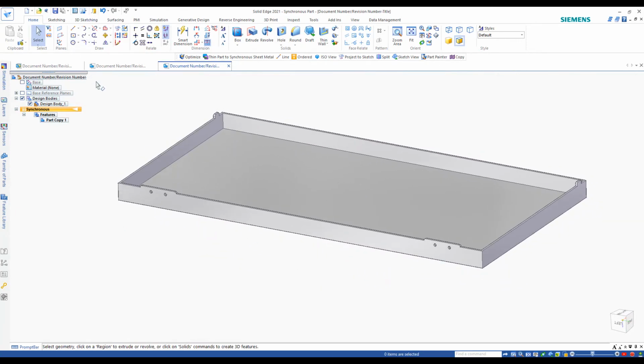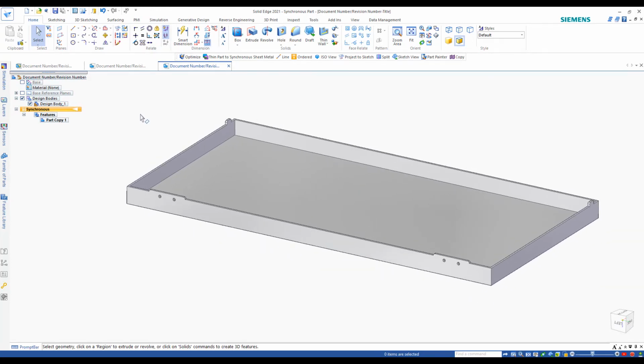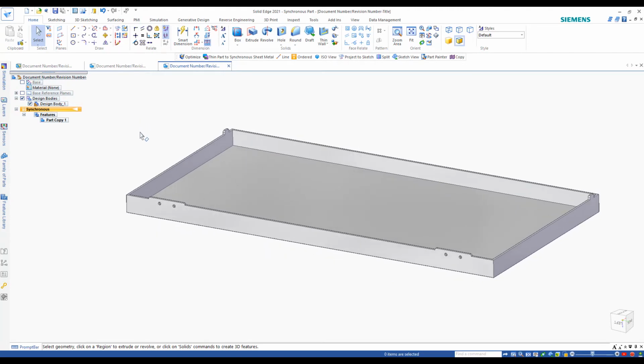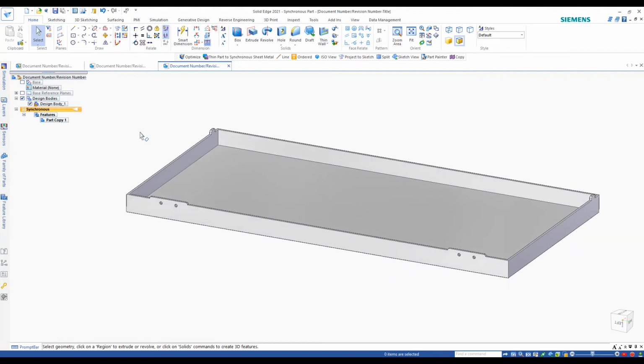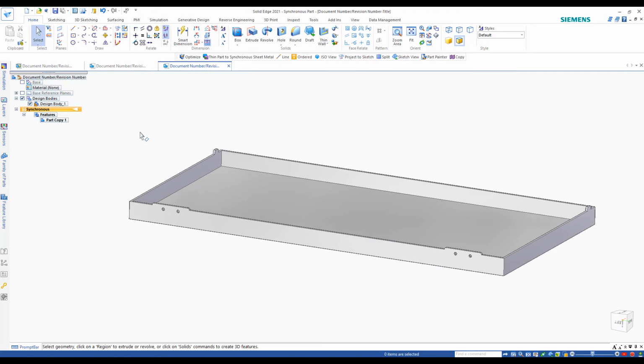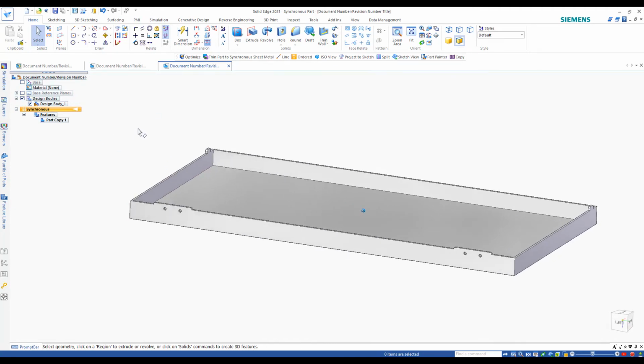One of those is utilizing a tool where you actually rip the corners first. The other one is another tool where you can do what we call part to sheet metal, and that will allow you, really, if you just modeled a cube, you could essentially take that cube and have it take elements of that cube and have it create tabs and flanges automatically. So I'll show you both methods. Again, whether you're working in synchronous or ordered, this first example works in both areas.